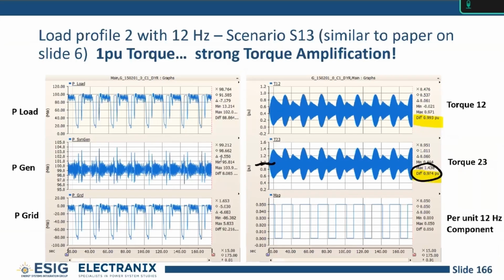I'm more worried about the big changes that will impact voltage, because the IBR plants can be a little sensitive to over voltage and under voltage. I think the only other consideration would be type 1 through 3 wind. The old ones or the type 3s. Yeah. But I don't think we're seeing the cell blow up, right? It's probably more in the world of slightly reducing life, right? Because the resonance could change the speed that you're spinning when the wind is still maybe spinning. So it could be a little bit of extra stress, but I don't see it.